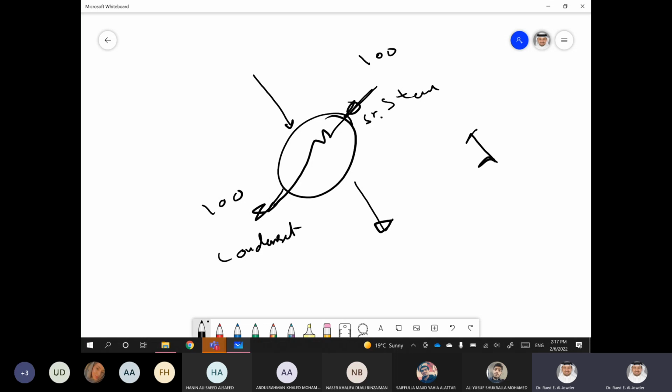Now, if you want to do it with superheated steam, to supply this process stream with the same amount of energy, you would have to go from, say, 130 down to 100 or 90 in superheated conditions. That is around 40 degrees Celsius, a big range. In the saturated case, we don't need a big difference; all we need is to supply it with lambda.